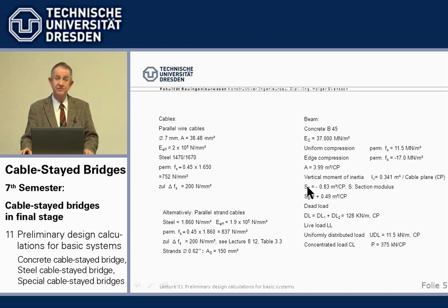One little difference, what we call in German Widerstandsmoment, and use a W, in English is section modulus, and we use an S. So the large S, top ST, section modulus at top would be in German W oben and S bottom. Otherwise, we have a little bit different nomenclature. Our dead load, small g, is DL, dead load in English.